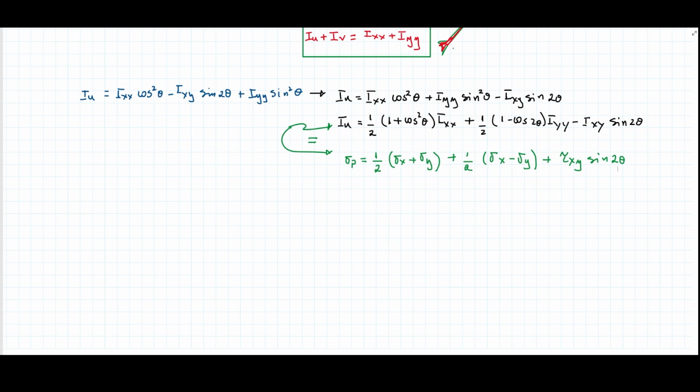So let's remember that when we're talking about stress tensors, or in this case, a stress element, if I had this case where, according to my loading case, I'm going to have this sigma x, this sigma y, and then on the top, for example, these shear stresses, tau xy, and this one here also tau xy. This arrangement is going to give me a matrix like this one here. This is the simplification in 2D.